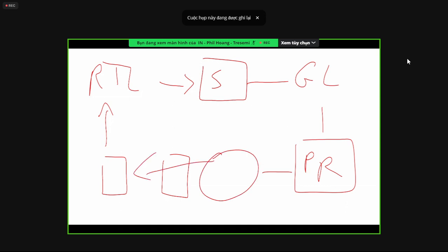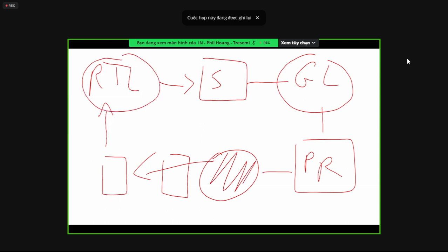So this gate level netlist is what you're talking about, but IP comes in two forms. One is the final layout. Two is from the RTL level. The reason for RTL is that RTL is technology independent. When you do synthesis, say you have to do 22 nanometer, a technology is already attached to this netlist.